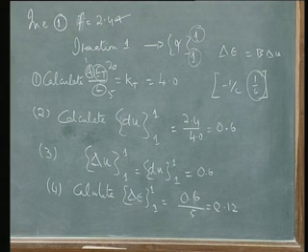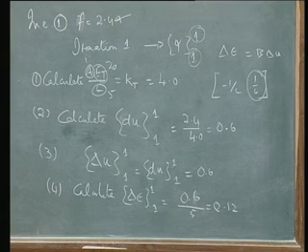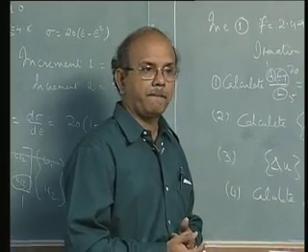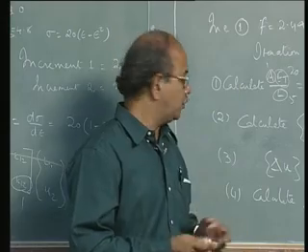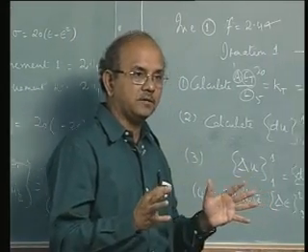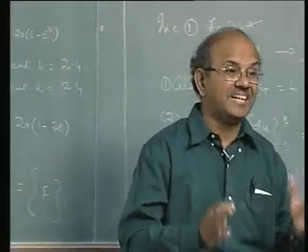So having done that, what's my next step? Fifth step. No, it is not that we determine KT. I still have to determine stress, look at the error, and only then decide whether to go to the next step. Usually it's a good practice at this point to calculate the total epsilon. Total in the sense not only for this increment, but total till this increment.